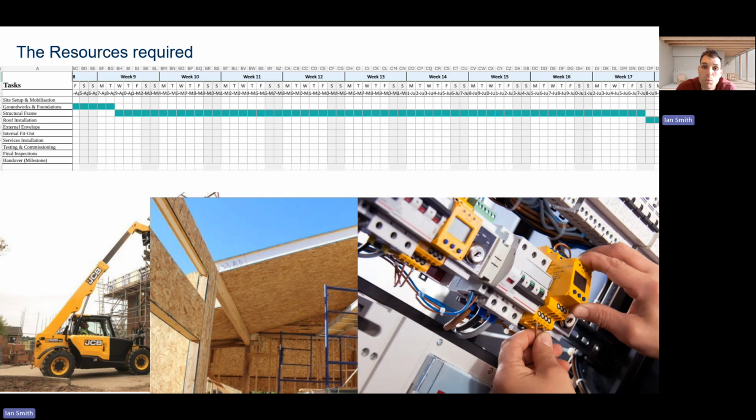The last material we are going to look at, or the last two, sorry, are our building envelope materials such as blockwork, timber, cladding, or as we can see here, SIPS panels, which is what this restaurant is specified to be constructed out of. As we're using SIPS panels, these can be delivered to site and erected quickly and will form the envelope of the building. Any that need to be stored will be stored in the appropriate material storage area and will be protected from weather and damage to ensure the quality.